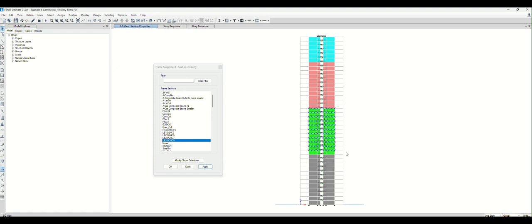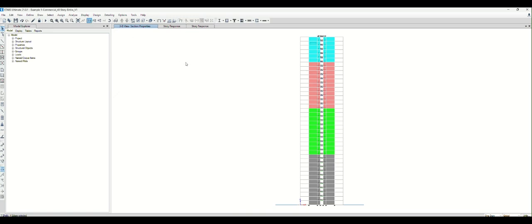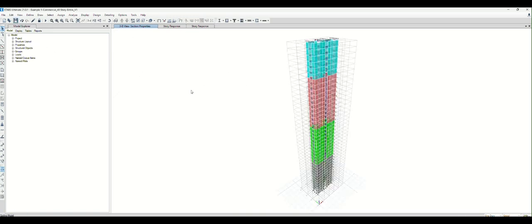And then I'm going to select and assign 22 by 24, which is matching, and also 20 and 18. So wall thickness and beam width are the same, matching, right? So I think this is just quickly I assign randomly the wall thickness and associated wall concrete strength. So let's run it.